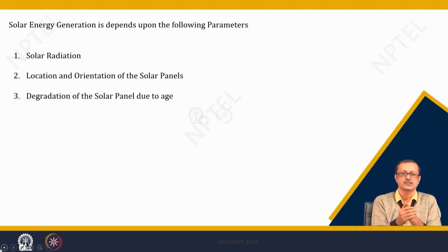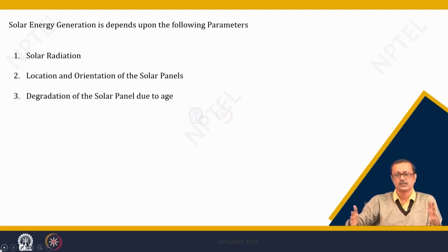Sometimes it may be broken because of mishandling or something like that on the rooftop. Maybe some kind of cyclone may cause some degradation, that is the external degradation. But during the ages, or due to the old age of this particular panel, because of the material over there, it has a kind of degradation. So, based on that it is better to calculate the areas based on the modular efficiency, not from the watt peak per meter square or so.